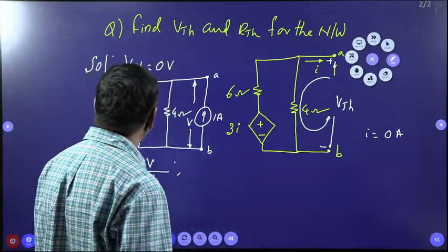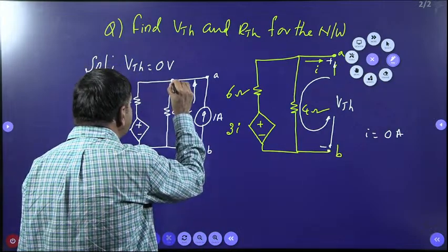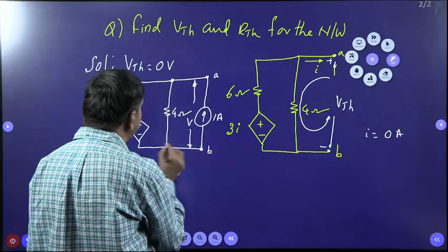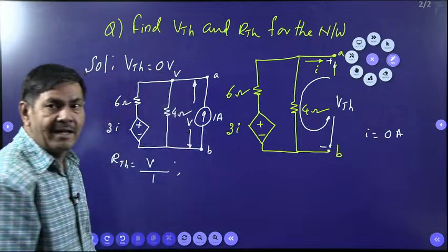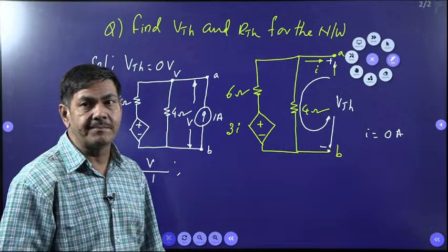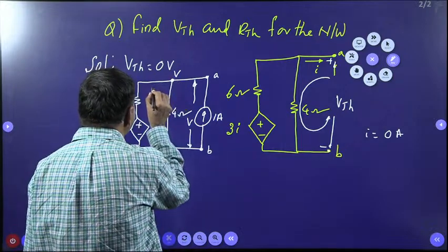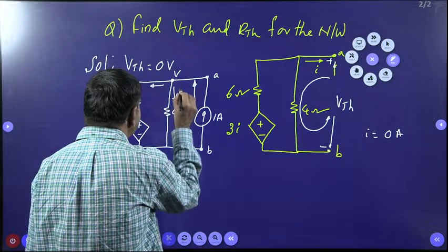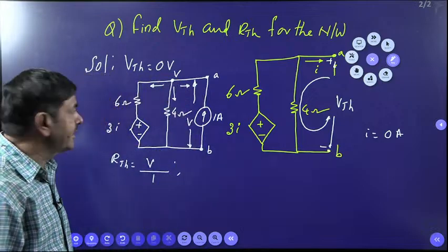How can we find this V? This voltage and this node voltage are the same, since we don't have any other resistance between these two terminals. This voltage, the same V, I can put. And I can apply nodal analysis. How can we apply the nodal analysis? Away from the node, I can select the current direction. This current plus this current plus this current equals 0.